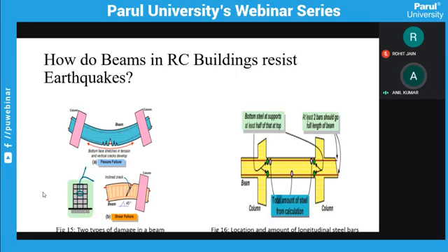At least 2 bars should go the full length of the beam. We can say that 2 bars are going the full length of the beam, from one end of the beam to another end. And these stirrups, you can see, these are the total amount of steel which we are going to calculate, the total amount of steel which we are going to provide in the beam design. So whenever we are designing a beam, we have to check that these two types of failure should not be there: flexure failure and shear failure.